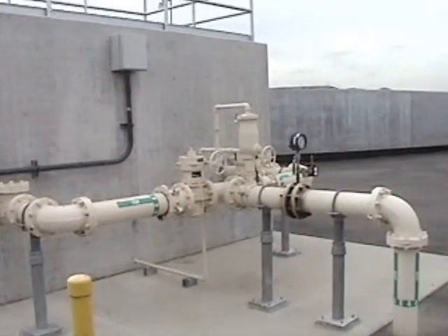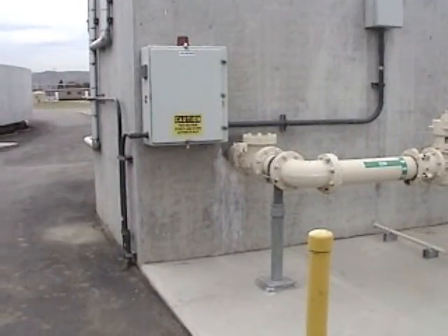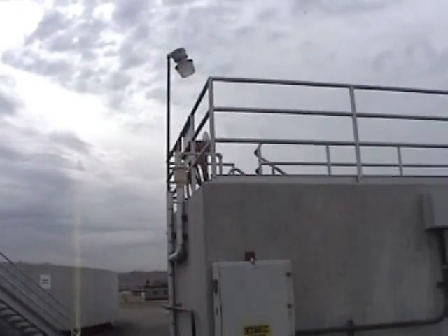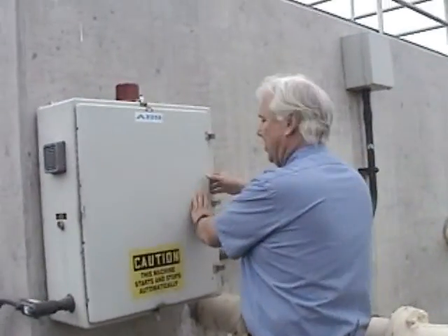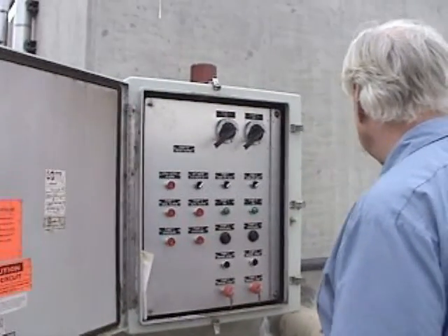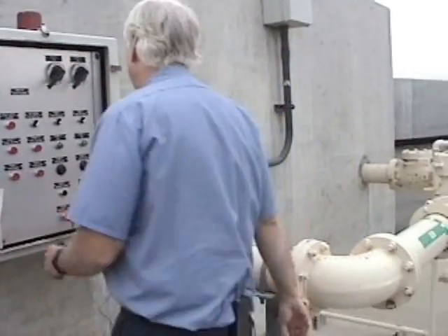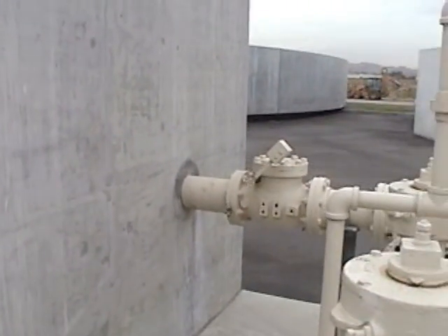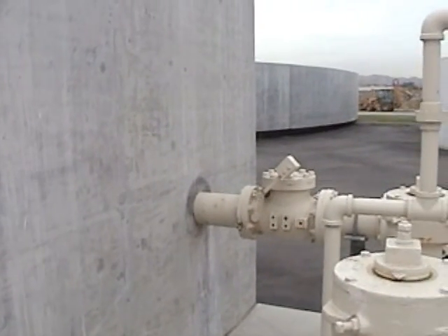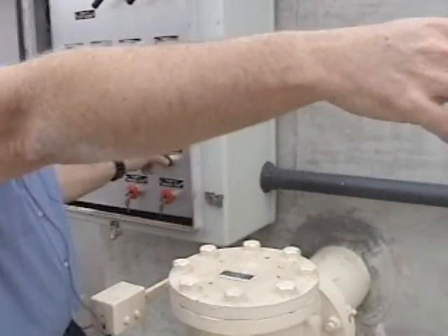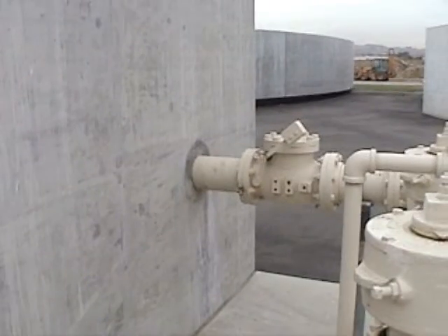And if you find that you can't pump from this tank, to reestablish pumping the best thing to do is open up the panels on the top, and then begin flushing with water. If you're coming over here and you get an alarm on the SCADA system and it's high scum well level in this tank, you'd come over here and make sure, see how that check valve is open right there? So if you had a high scum well level, you should see that this pump is on, and either one pump or two pumps are on, and you can tell the pump is on. You can see from that float that it's on.